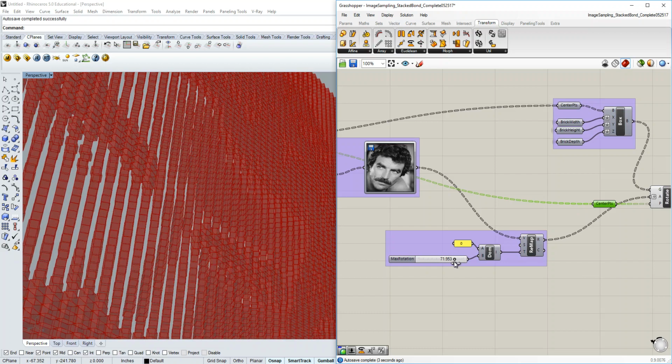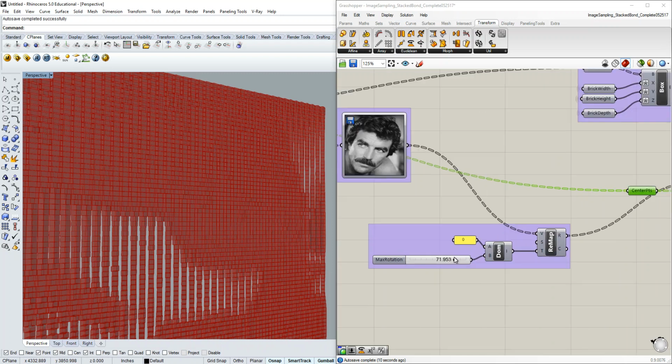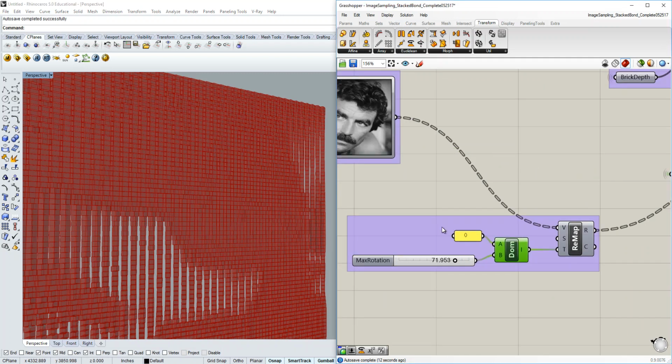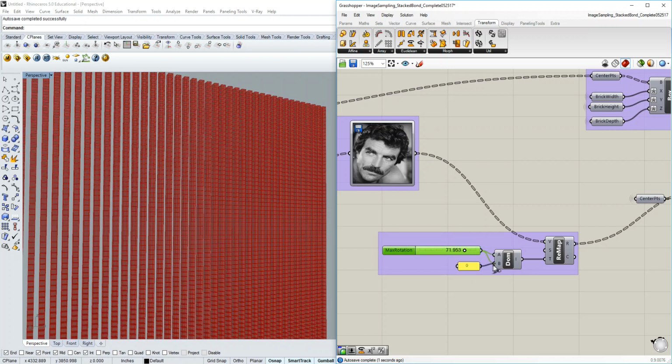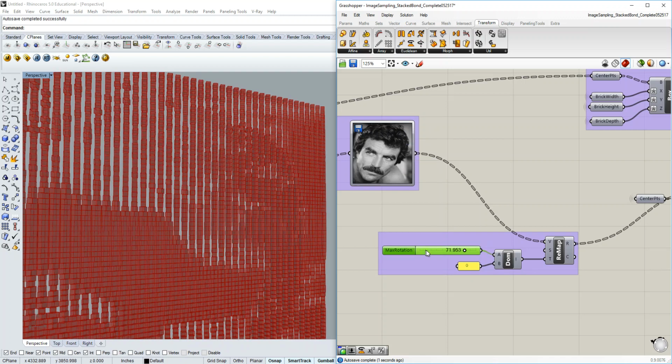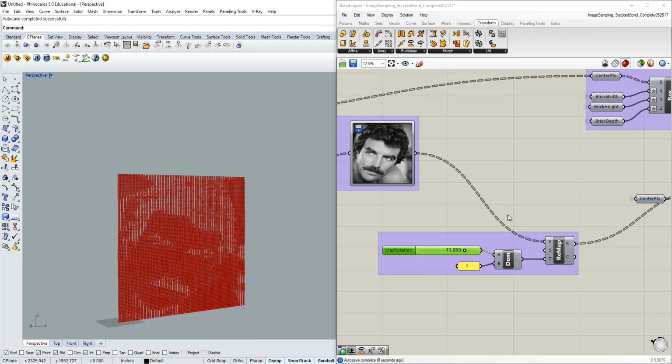And if you want to invert the image, essentially make all the black ones white and all the white ones black, all you have to do is swap the A and B of our domain. Now all the things that were black or 0 for brightness currently are 0 for rotation. If we want to have those to become the maximum rotation, just swap the A and B inputs of our source domain. Now those that were once 0 for the value now get the maximum rotation angle. Those that were the brightest get the minimum rotation angle. That'll allow you to kind of invert the image itself.